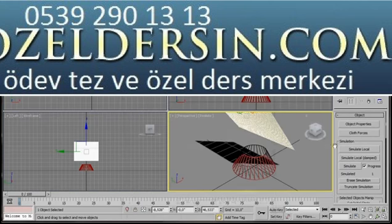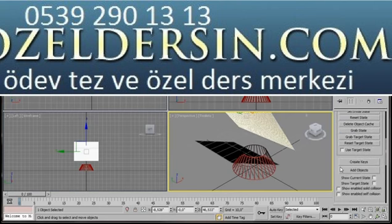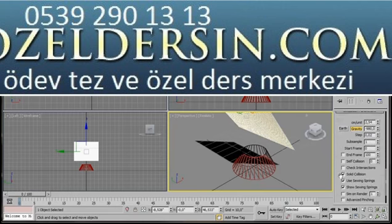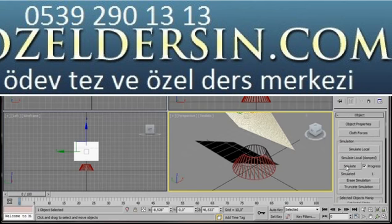Now let's go back over to the panel and we're going to scroll right down to Simulation Parameters. And we're going to turn on Self Collision and set it to 1. Also we're going to turn on Check Intersections. Now let's scroll back up again. Everything's ready now to start our simulation, so let's press the Simulate button.